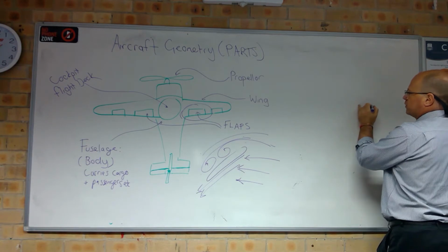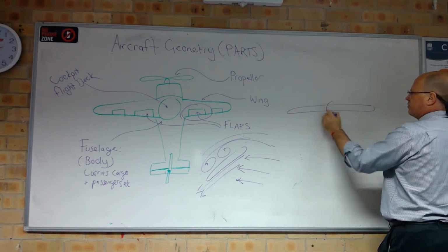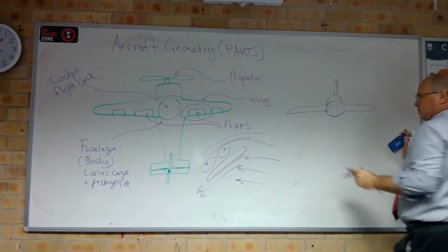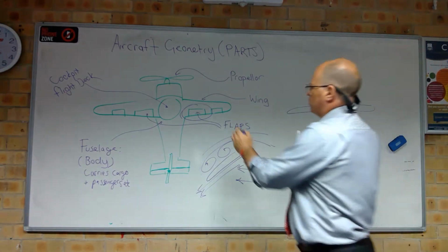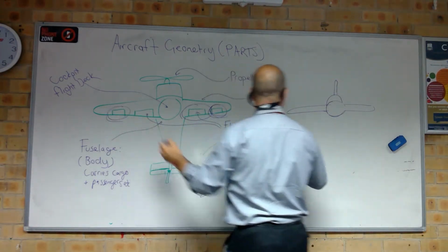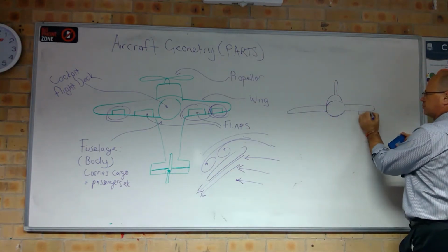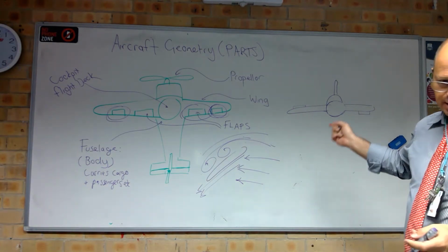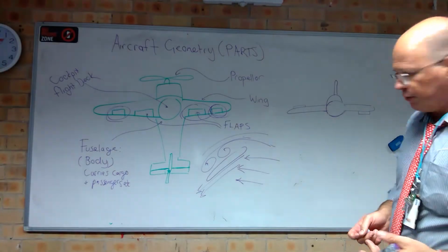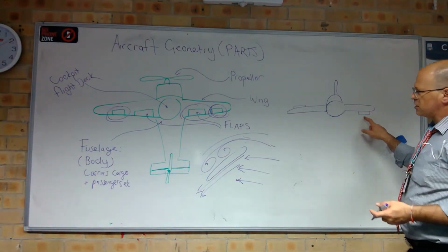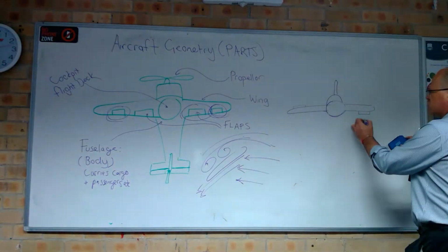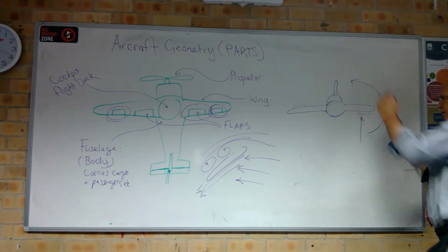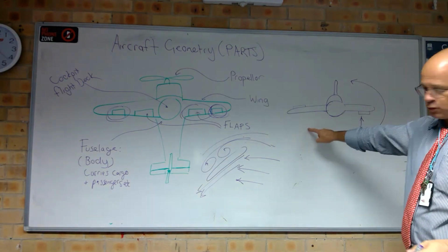Okay. So if you were to look at the wing or the aircraft from front on, what happens is our ailerons, which are on the outside of the wing, one will come down and one usually goes a little bit up, okay? There's a reason for that one going up, and we'll talk about that another time. I don't want to confuse you, but when that one goes down, it's just like when the flap goes down, it increases lift. So if this wing has increased lift on it, okay, the aircraft is going to roll that way, okay, because it's pushing up more than this wing, okay?